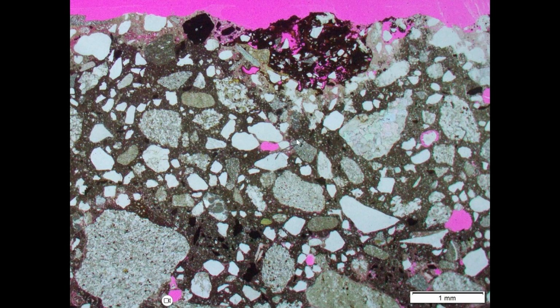When I looked at this under the microscope, when I was doing my petrographic work, this is what we see. So now we're looking at that in cross section. The pink color at the top represents the surface of the sample. This black colored blob at the top is a cross section of one of those embedded steel strands, and you can see that it's rotted out. It's got holes in it, and it's clearly not a solid piece of steel anymore. It's got roughed up quite a bit.